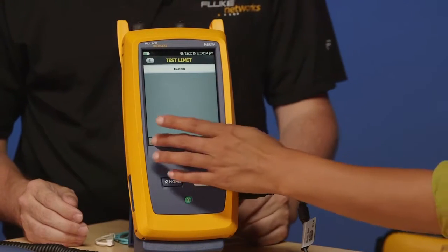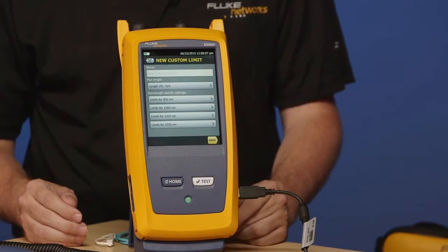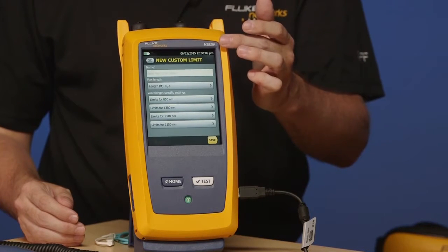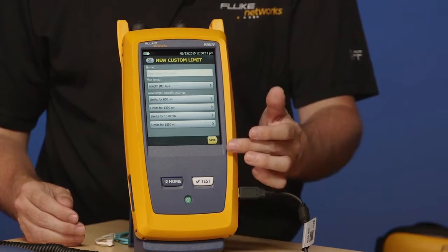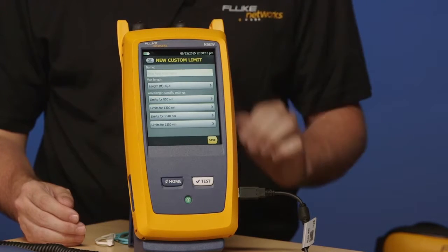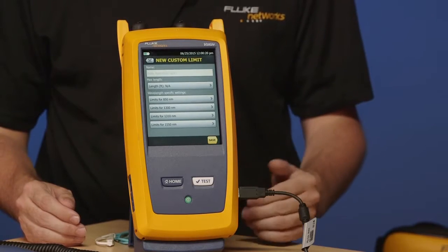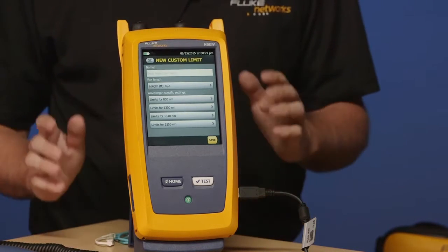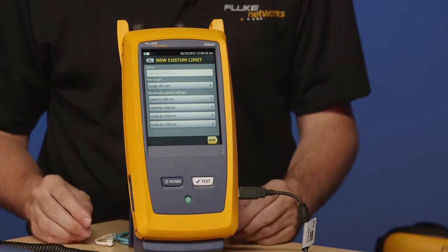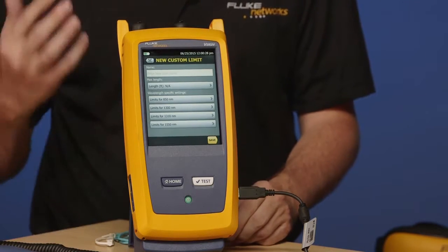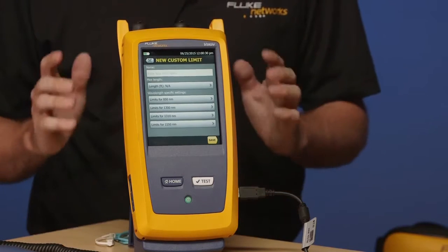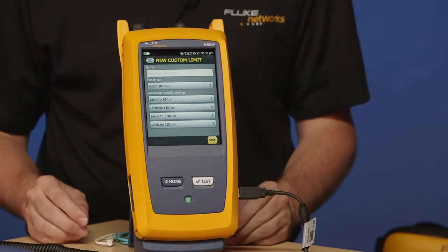With OTDRs, a lot of people like to use their own test limits, and you can do that with the OptiFiber Pro. Go ahead and tap on Custom for me. And yep, we're going to go and create one. Excellent. So we can put the name of our custom test limit in the top here, and we have the 4 wavelengths that are supported with this module here, both multi-mode and single mode. So we can go into those menus and add in our connection loss, our splice loss, our fiber loss, and test to a tighter specification. That's very common with OTDRs, which again is another reminder, please check your test specification. You don't want to be retesting because you selected the wrong test limit.